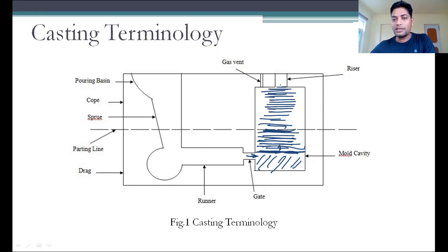So as it is coming out, which material is this? It is not the material which is recently added. It is the material which entered at this cross section area when the molten material height was this h, we can say. The molten material which is coming out from this area now, the riser, was filled before, not recently. Whatever molten material is coming out, obviously that will be in the liquid form.